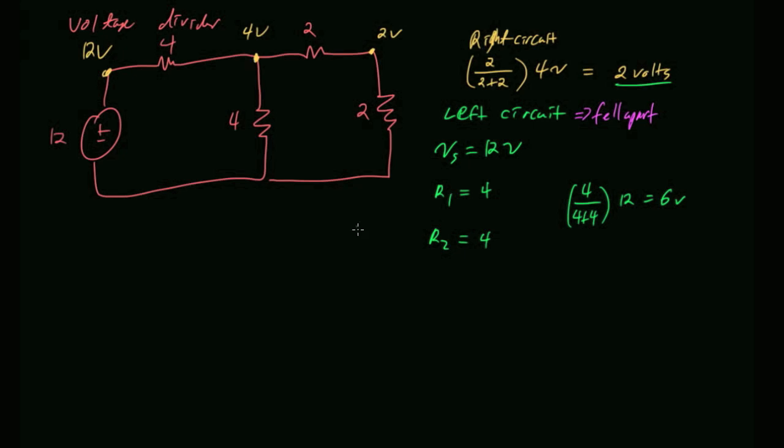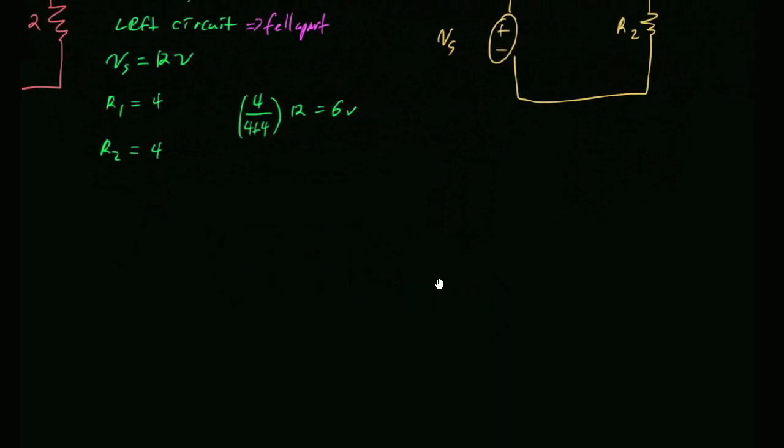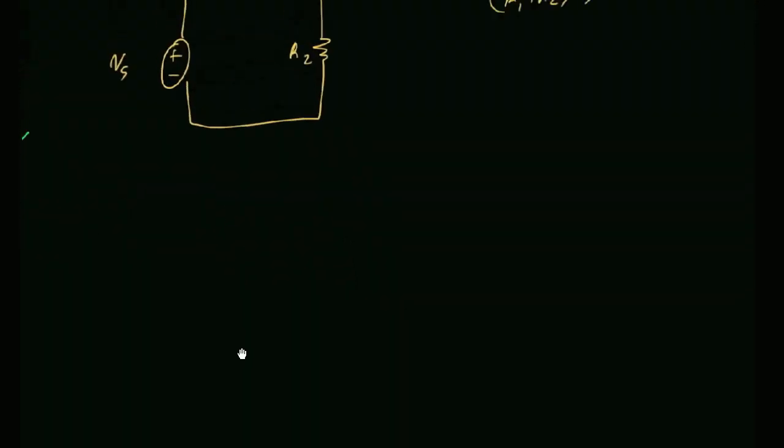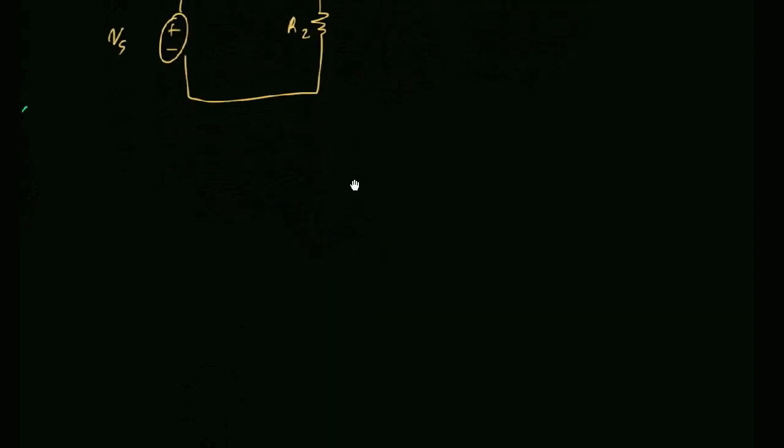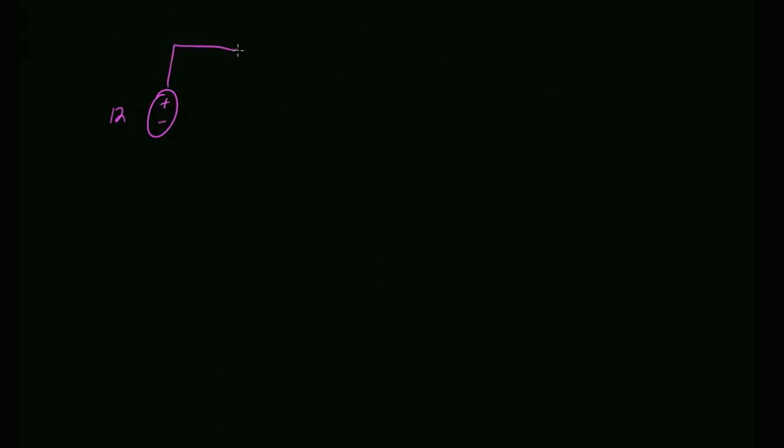Let's say, for example, that I just built this circuit. So 12, 4, and 4. Yes? So that's going to be a voltage divider. Well, I guess the voltage divider won't actually work for, you're going to have a resistance on your output. That's right. The voltage divider assumes that all the current that goes through this resistor goes through this resistor. That's how we did the calculation, right? Well, when voltage divider was derived, literally the way we derived it is that all the current that went through R1 went through R2, right? As long as that assumption holds, we're golden.